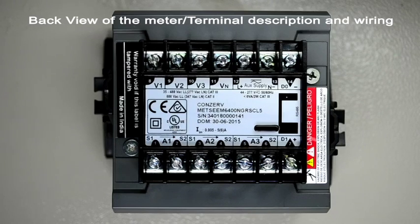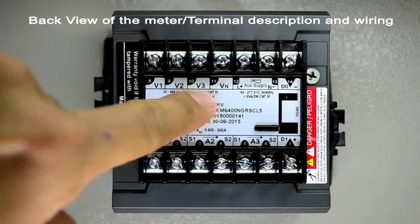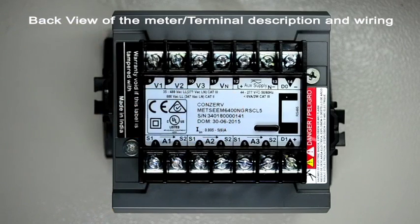View of the meter showing the terminals for connection. V1, V2, V3 and Vn indicate the voltage terminals. For category 3 systems, voltages of up to 480 volts line to line can be directly connected to these terminals. Voltages above 480 volts line to line should be connected through external voltage transformers. For category 2 installations, voltages up to 600 volts line to line can be connected directly to the voltage terminals.